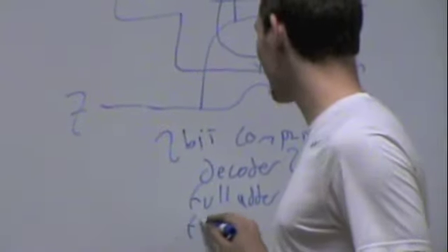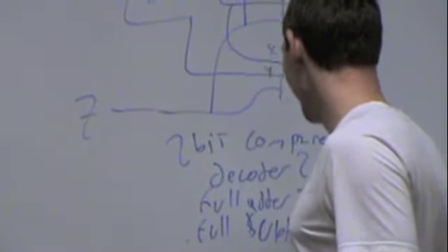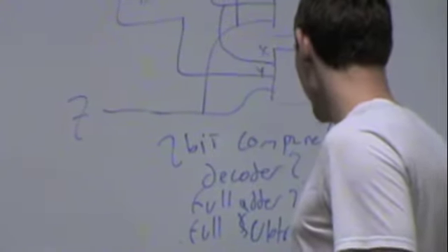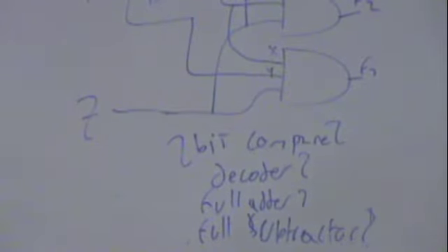And then the last one is a full subtractor, which it definitely is. Clearly. All right. Just for everybody on camera, why is it not a full adder or a full subtractor? Full adders I know have exclusive ORs in there. They have exclusive ORs in there. Yes. It's two half adders which have exclusive ORs and AND gates. And it's not complicated enough for an adder. It doesn't have 4 outputs either. That is true.